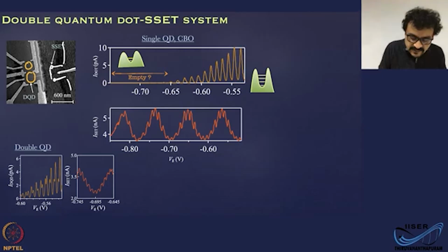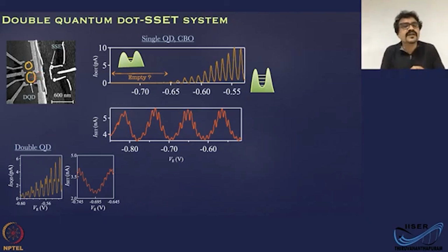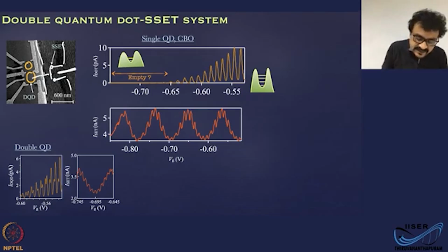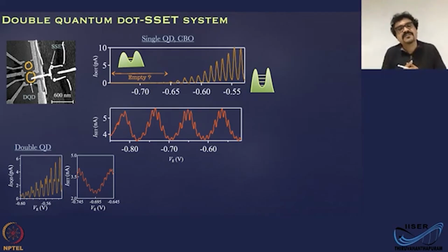And this is the gate for the SET, and there is an edge here which makes sure that the electrons in the quantum dot do not escape out here. So the path for electrons is dot 1, dot 2 and goes out, and the sensor extends onto one of the dots just to improve the capacitive coupling. Okay, the sensor island here is extended to, you can see a weak, feeble image of a line which is going on top of the quantum dot. That is to improve the capacitive coupling.